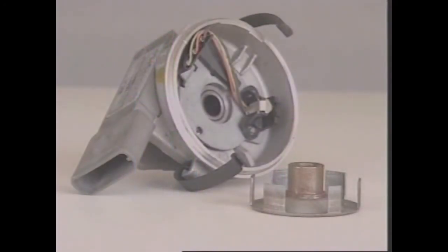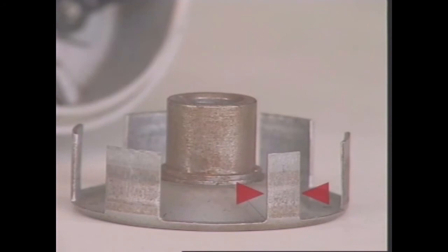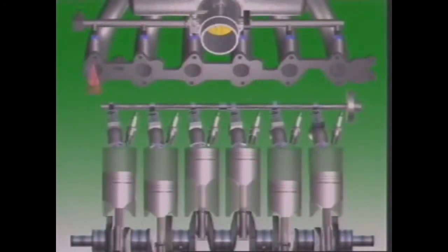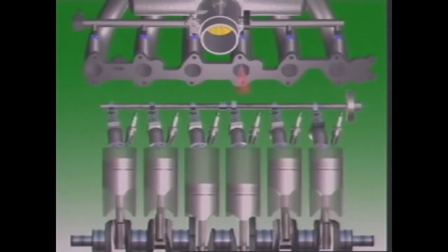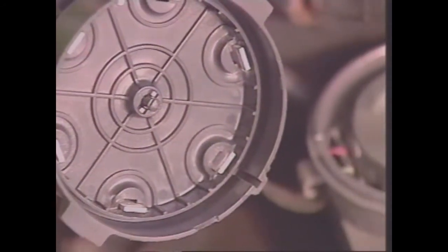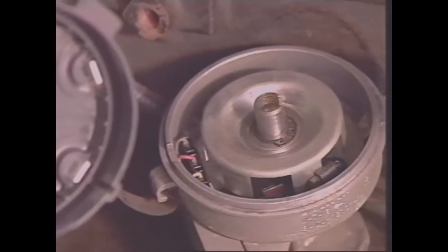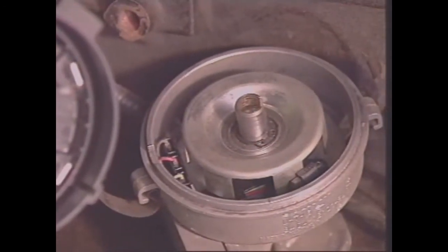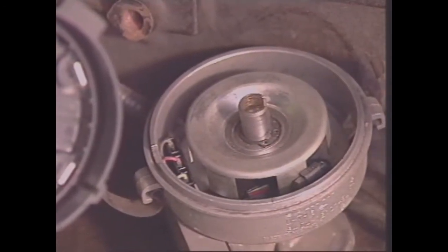If a sequential injection mode is used, the position of the camshaft must also be signalled to the control unit. This is done by making one blade of the interrupter ring shorter than the others. It's called a signature blade. It passes through the sensor and alters the signal, so that injection commences at the correct time in the cycle. Since the distributor rotates at camshaft speed, the sensor in the distributor provides camshaft position readily.